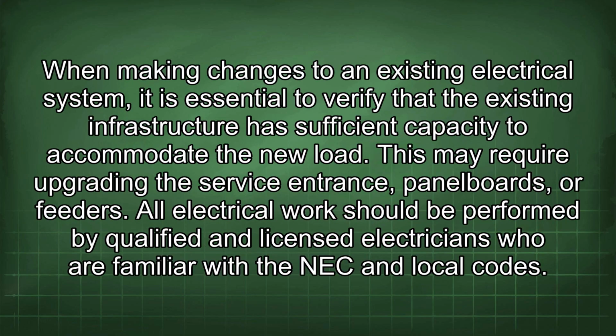When making changes to an existing electrical system, it is essential to verify that the existing infrastructure has sufficient capacity to accommodate the new load. This may require upgrading the service entrance, panel boards, or feeders.